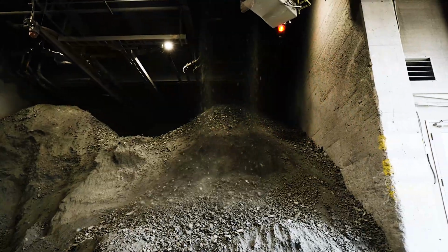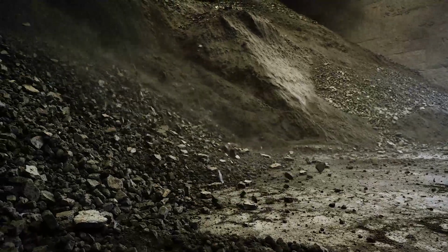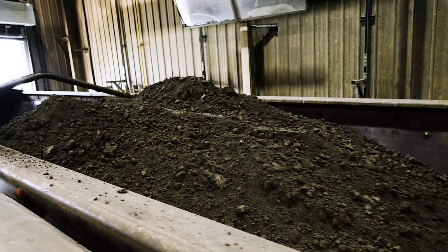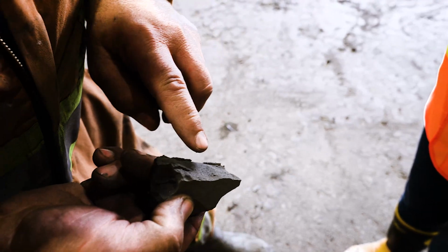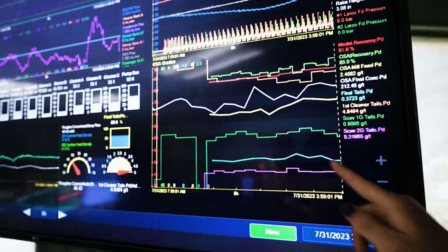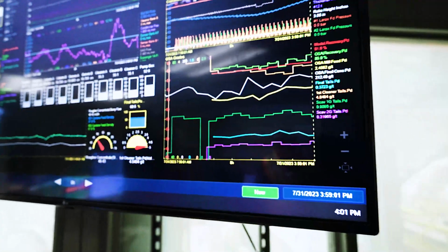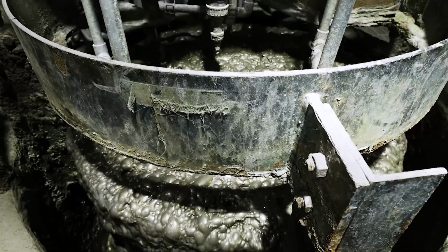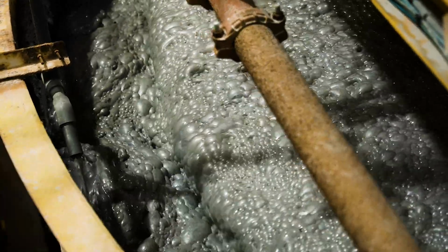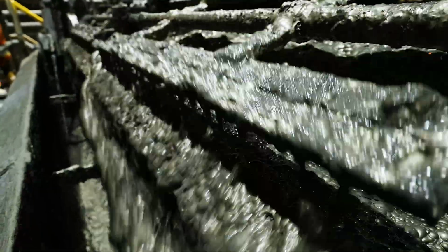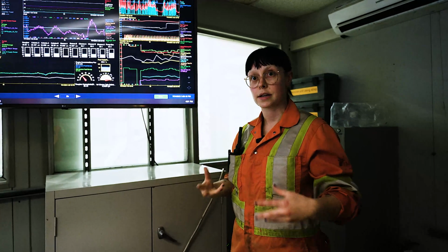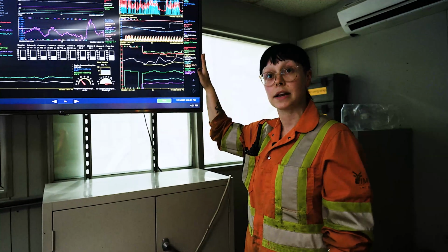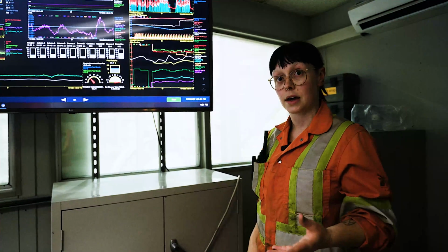We're also monitoring our final concentrate, which is our final product, so we want to know what our grade is of that concentrate to make sure we're hitting our targets. Similarly with the final tails, which you see in the blue here. We want to keep our final tail low so that we are getting as much palladium and precious metals out as we can. Out in the field, our flotation operator is monitoring this constantly to make sure his circuit looks good when he's pulling, but now we actually have the data that can help him confirm that that's the case.